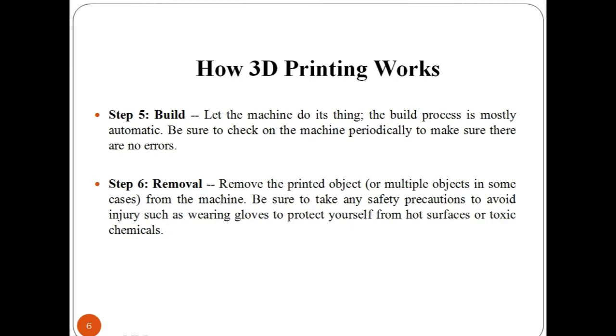Now the next step is removal. Remove the printed object from the machine and be sure to take any safety precautions to avoid injury, such as wearing gloves to protect yourself from hot surfaces or toxic chemicals.